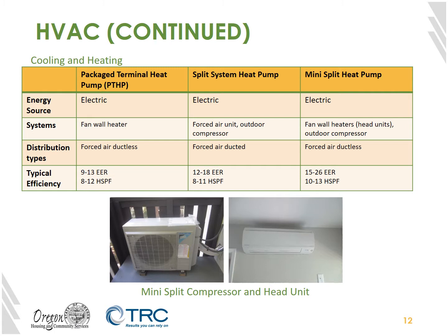Heat pumps are available as package terminal units, outdoor compressors of the same form factor as air conditioning units, or as mini splits, shown here. These still have outdoor compressors, but use individual head units to deliver conditioned air and require no ductwork. As a result, they are typically the most efficient option.